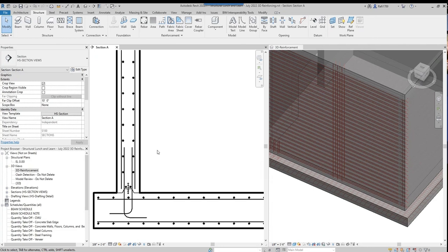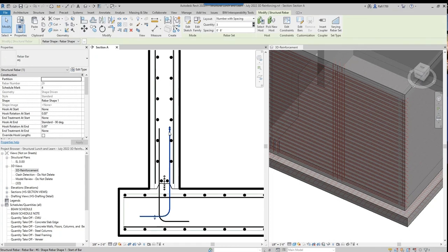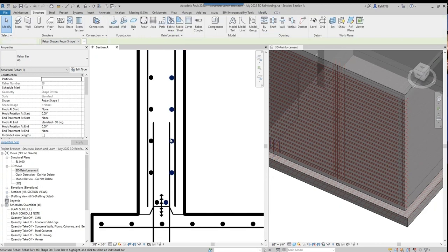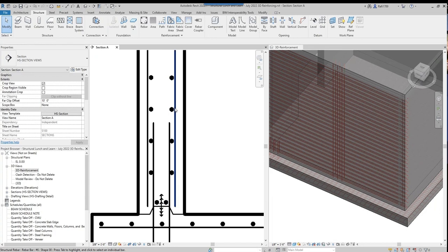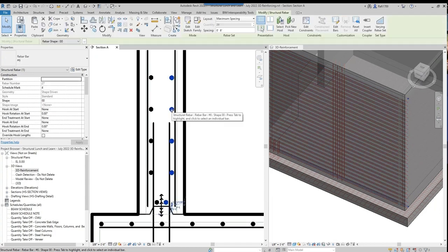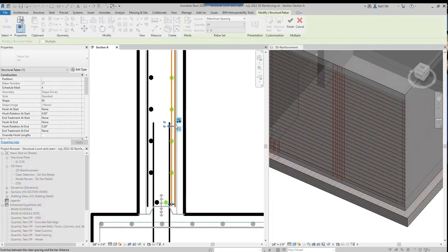All right. So once we have this exactly how we want, here's the thing. At least in 2020, and I haven't fully tested. Well, actually, I'm lying. I did this in 2022, right? You have to kind of reestablish some of these constraints that aren't automatic. So these two, because they were mirrored together, maintain their constraints. You see, they still have that two-way constraint.